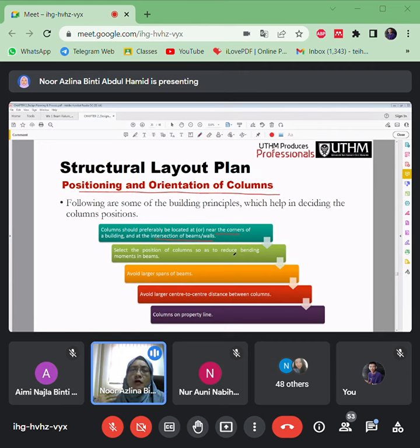It will affect the vibrations process, the concretings and everything, okay, and then we have to ensure that all the surroundings of the reinforcement also are coated with the concrete mix, kan, so kalau terlalu banyak reinforcement, that is actually we want to avoid.